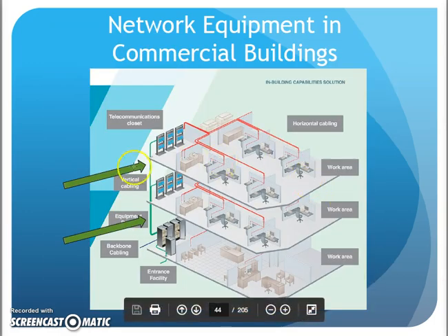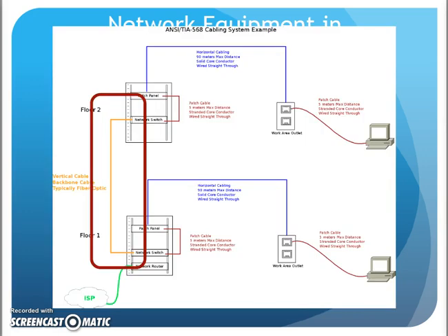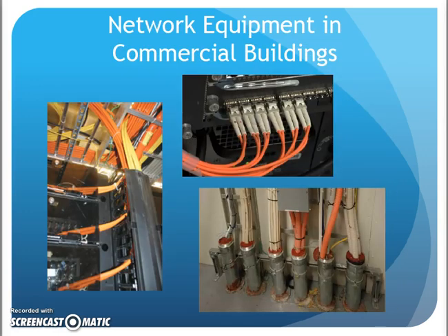Okay, there is your backbone cabling between your floors. So there it is right there. Those sleeves to the floor, fiber cables going between closets. That is your backbone cabling. Again, more times than not, fiber optic cabling connecting your closets together. Fiber for distance and bandwidth.